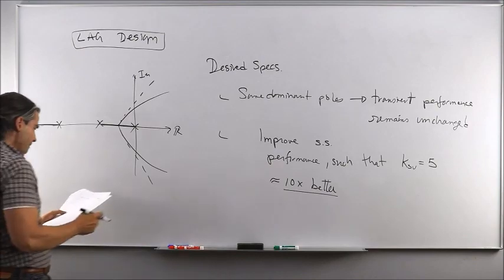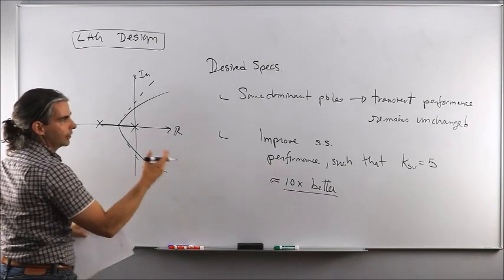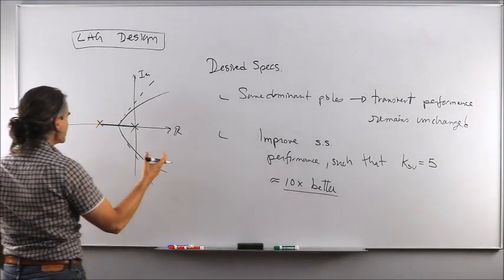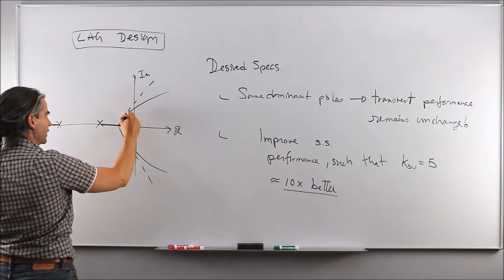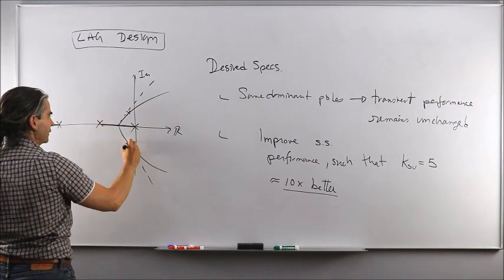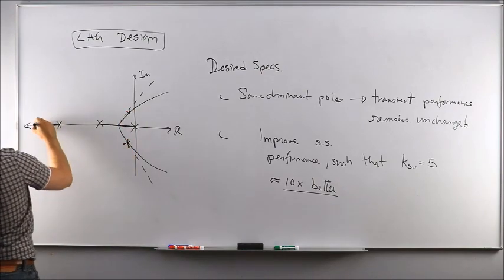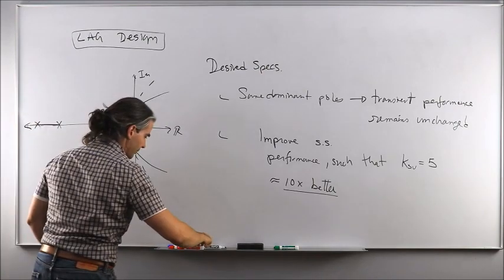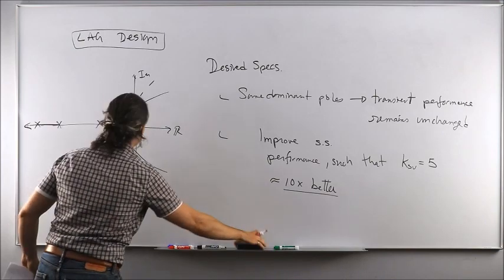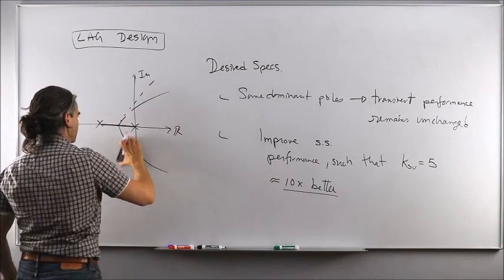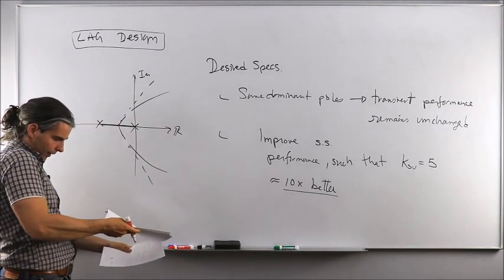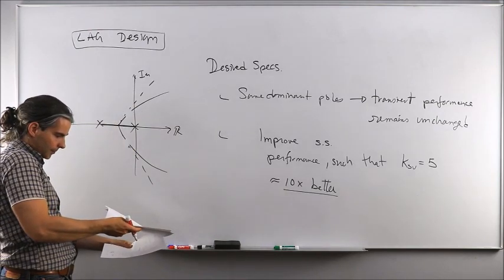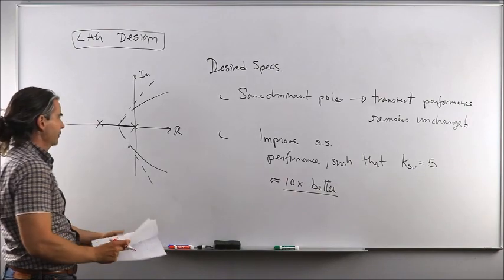Okay, so the poles I had given you from the closed loop transfer functions ended up being somewhere here, there, and over here. And let me draw them in red. And these were, for completeness, the minus 0.33 plus minus 0.5864j.